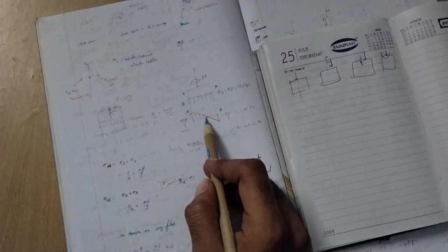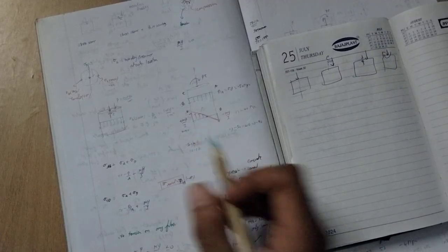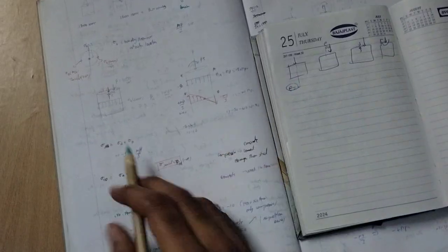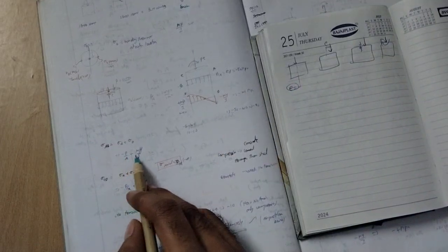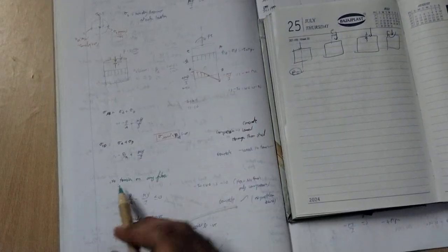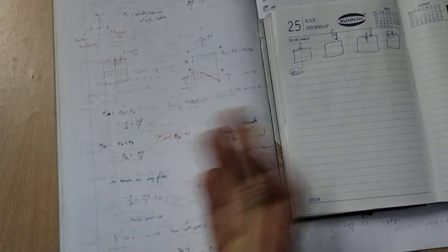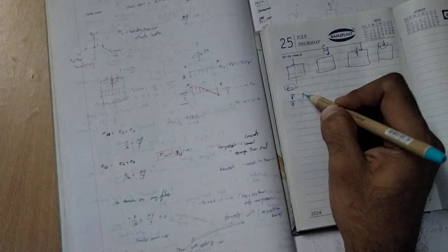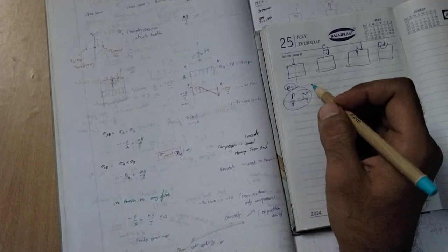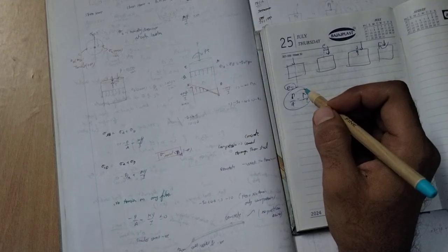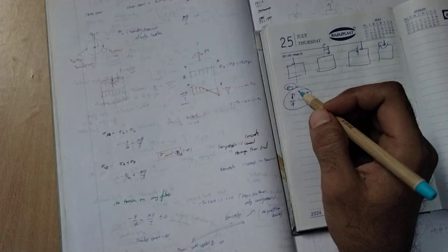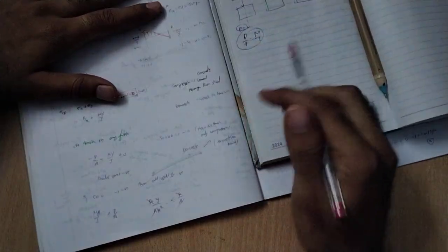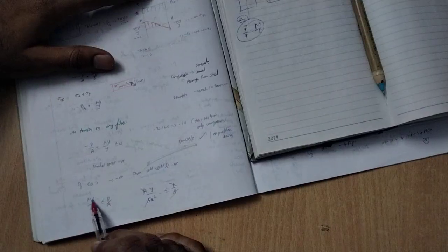So generally there will be a neutral axis. We don't know the eccentricity, so at that eccentricity the entire thing will be 0. So you can see direct stress minus P by A due to this, on this side, so no tension in any fiber occurs on one side. At that time both will be equal. So P by A equal to M y divided by I. So that will be the same, equal to M y divided by I.